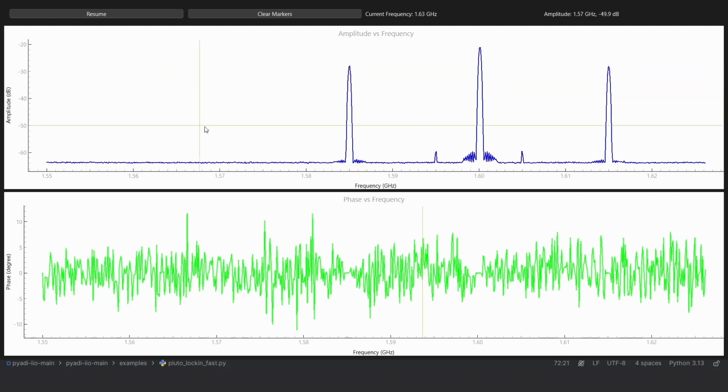One thing to note here is that you can see the tones 15 megahertz apart from the main tones. The second sine wave has an amplitude in dB that is about 8 dB less. One of the reasons for that is because we will see minus 100 kilohertz here and plus 100 kilohertz here, and there is a chance that because of the accuracy of our RxLO, they are mixed together. So we are seeing the equivalent power of them added into just one tone here.